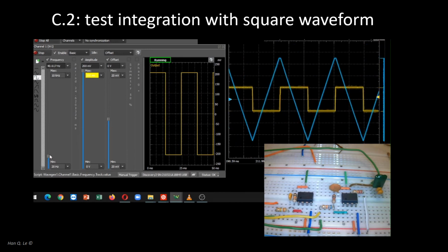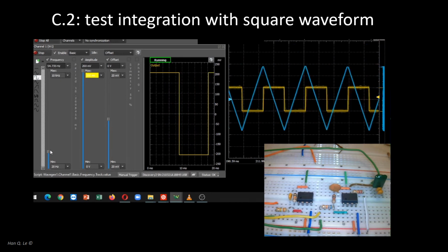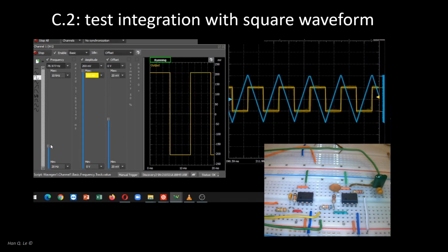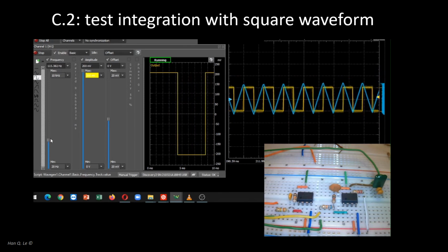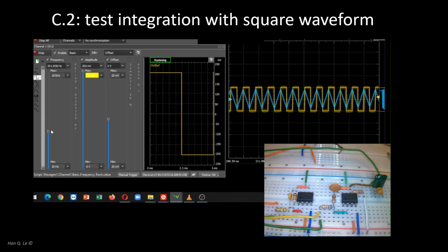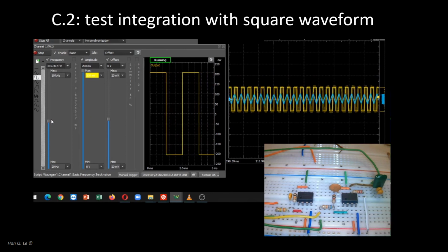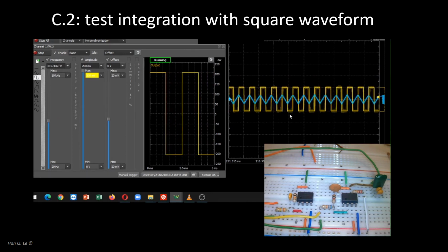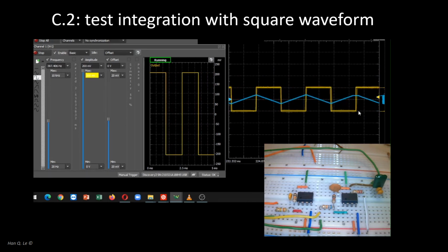As the frequency increased, the amplitude of the output triangle wave decreased as expected, but maintaining the slopes, as it should be. Here, the decrease of the amplitude could be thought of as due to shorter integration time, because of the smaller period.